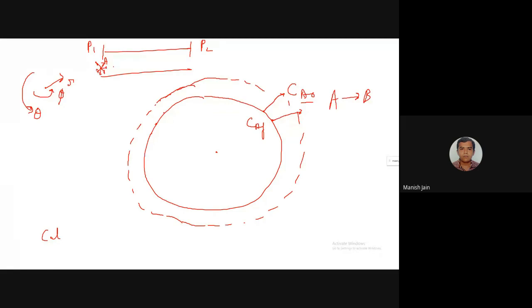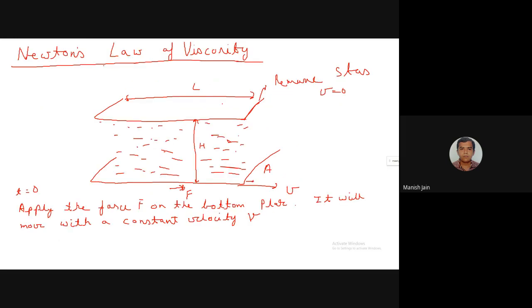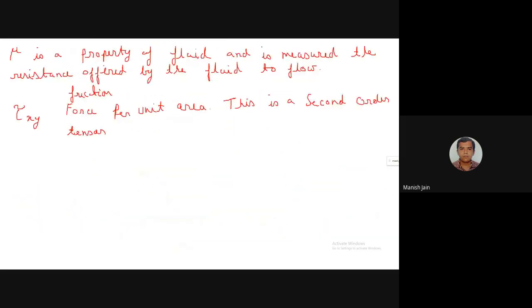Between point A and point B there can be a difference in pressure. Here the pressure is PA, at point B the pressure is PB, and PA might be greater than PB, but at a given point the pressure will be the same. There is no preferred direction of the pressure. So pressure is a compressive force, and for hydraulic pressure it is the same in all directions. That's why pressure is a scalar quantity, although it is a force per unit area.